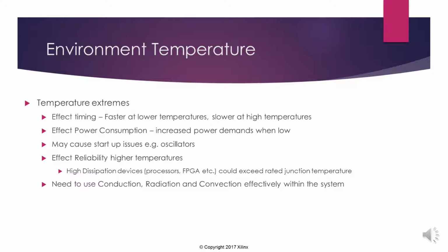It can also have an effect on power consumption when starting up at low temperature, when it's doing a cold start. We could see that we need a really increased power demand at the low temperature. I've seen this several times where we need to ensure that we've correctly scoped the power supply solution to ensure that we can address any startups like that. And we also need to address other things such as oscillators. Oscillators, crystals, they may take extra time to actually start up and get going and be stable before we can actually use them. So we need to take into account that worst case time to ensure that the oscillator is up and stable before we move on.